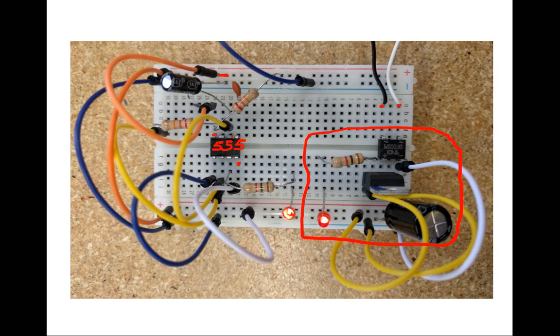And so we have this all wired up. Then these resistors, this is a 20 kilo ohm resistor, this is a 20 kilo ohm resistor, and this is the capacitor. These two resistors and this capacitor are what cause the 555 to oscillate and generate the waveform. Again, it's a charge and discharge of this capacitor through these two resistors.